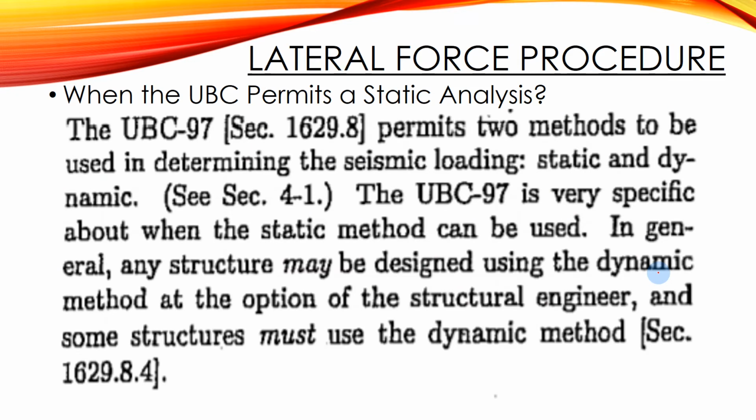Okay, so when does the UBC permit a static analysis? Kanusa pwede gamiton ang static or equivalent lateral force procedure. The UBC 97 permits two methods to be used in determining the seismic loading, static and dynamic. The UBC 97 is very specific about when the static method can be used. In general, any structure may be designed using the dynamic method at the option of the structural engineer. And some structures must use the dynamic method.